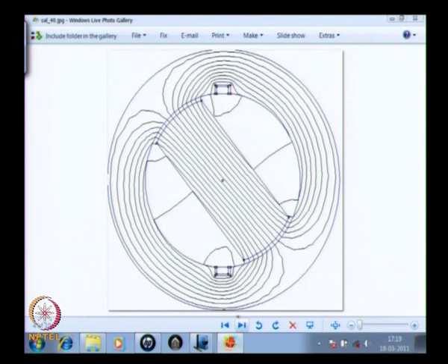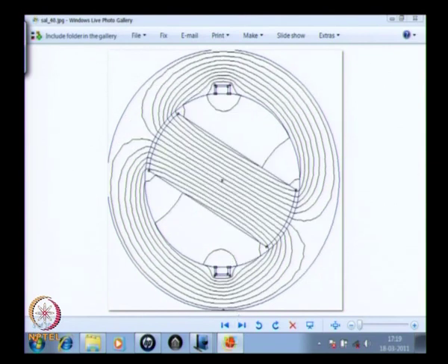The machine appears to look at it as if you are exciting the stator and you want to find out the flux that is thereby developed. Wherever the air gap is low, the flux levels developed are high, and wherever the air gap is high, the flux levels developed are low. Where the air gap is high or low will depend upon where the rotor is.